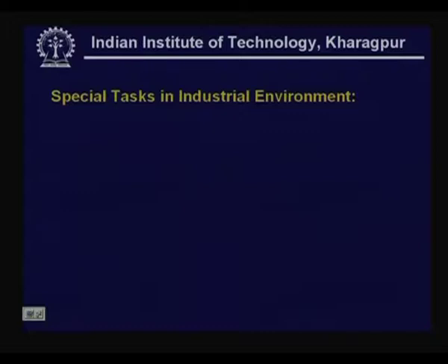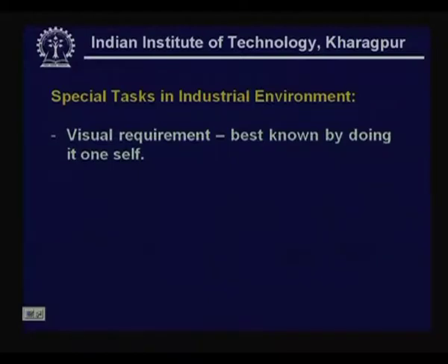And in that case, as I was telling you, if one needs to have good illumination on the work plane independent of the mounting height, the best thing is to have a matrix of lamps located within a luminaire. Don't have a single lamp. If you have a point source, we know that the illuminance varies inversely with the square of the distance. If you have a line source, which is the fluorescent lamp, it's going to vary inversely with the distance. And if it is a matrix of lamps forming a sheet of light, it will be independent.